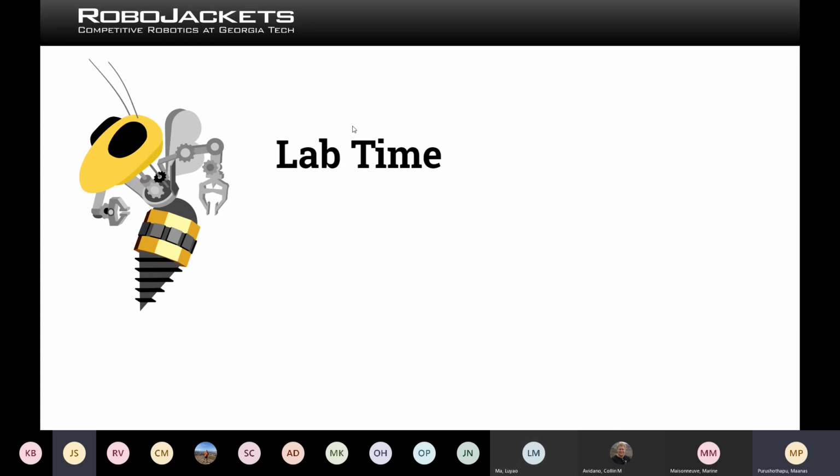Yeah, so to Lana's point, timer interrupts exist, and they are a bit hidden away. If you want to use them, you have to use port statements, which is like the lower level HAL. So it's not very explicit in Arduino. You have to use one step lower than that, but it's doable. But to Manos' point, it's not very common or advertised. If you have to do it, you're going to have to learn a lot more about how the ports and stuff work. So it's doable, but definitely not an intro thing. But good to ask about.